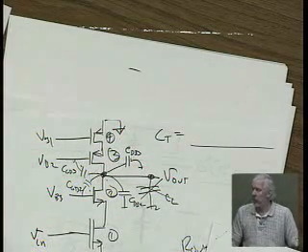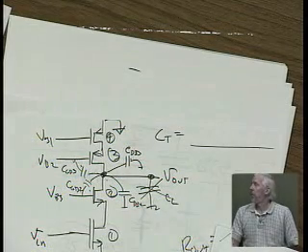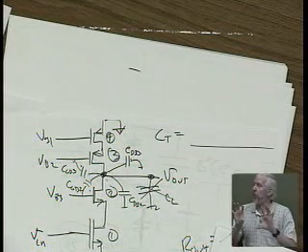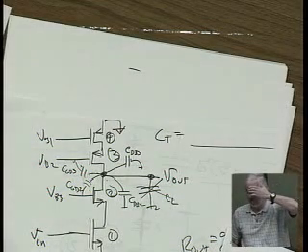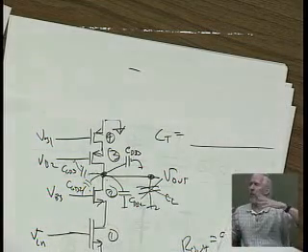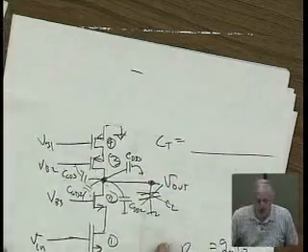Check the capacitors. Check your output resistance. Make sure that's right. And check the capacitances, and see if one of them you somehow calculated wrong relative to what they did. Normally it's not acceptable for this. You should be able to get within 20-30%. Okay.